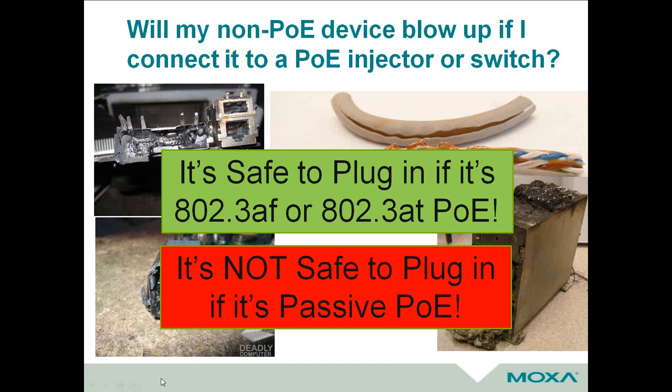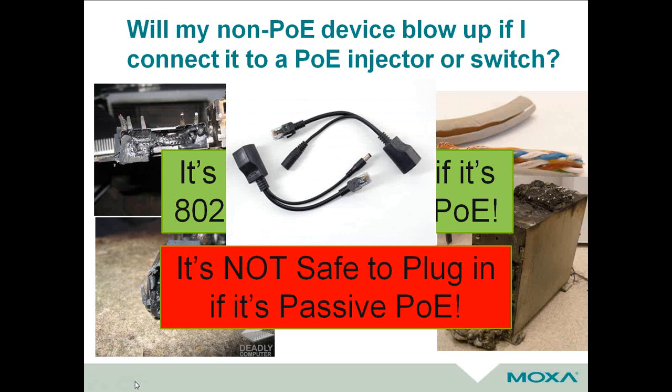Now, passive PoE works quite simply. What they do is they take an Ethernet jack and they literally plug in a power supply directly to it. There's no negotiation there, so there's no understanding of how it's going to actually work. So if you see something or hear something about passive PoE, please, please be very careful. This is not a good way to do a PoE solution. It's definitely a hack way to do it.